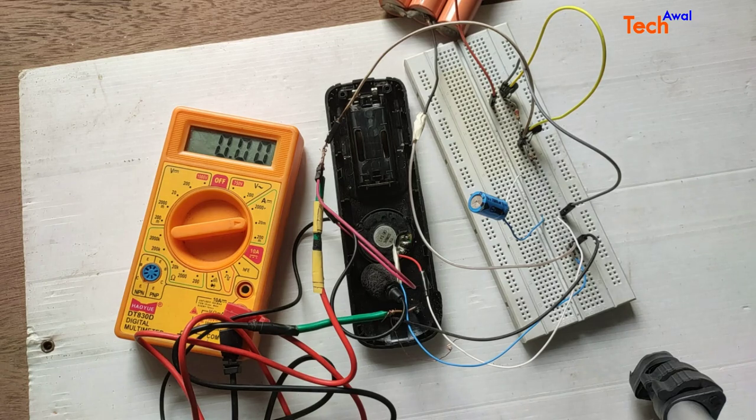Now the capacitor is charging. So when it is charging, there is no current in IE. Once it is charged, and when it is active, at that time the IE will be around 2 milliampere, and then the capacitor will get a chance to discharge on that path, and it will start reducing.